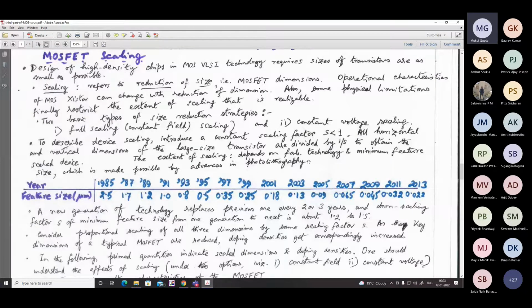Okay, several sets of masks are required, starting from the etching of the oxide, and then producing the source island, drain island. Then the overlying gate metal. And everywhere, the masks are to be made in an error-free way. For that, the advance in photolithography will matter. And definitely the fabrication technology.